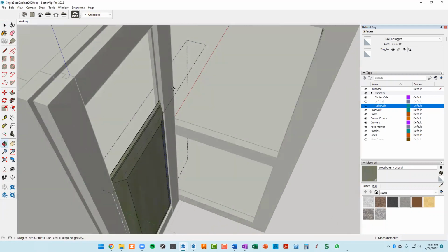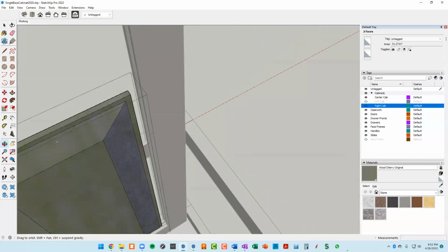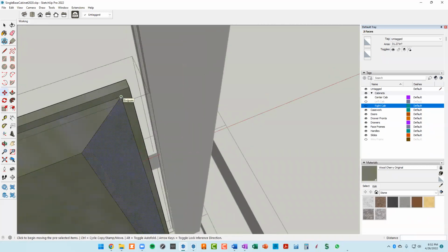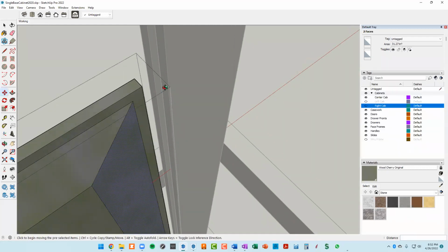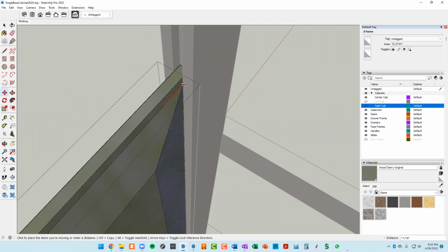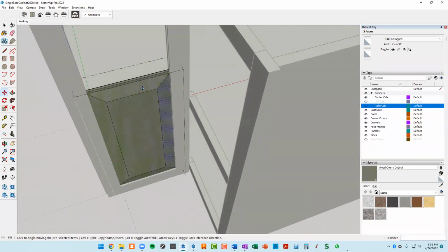So I'm going to hit Shift H to see the rest of the model. And I'm going to try to get it in the right position. Actually, what I should have done, I'm going to click there. I've still got those two surfaces selected. So I'm going to click right here because I can deposit that right against this face right here. So I'm going to move, I hold down my shift key and then just inference this face right here. So that horizontal dimension is proper now.